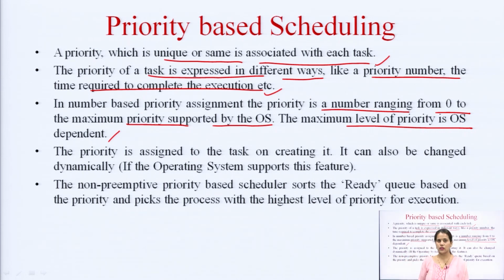So, priority is assigned to the task on creating it, and it can also be changed dynamically if the operating system supports this feature. So, based on the requirement, the priorities of the tasks can be dynamically changed according to the need, and so the different tasks can be executed according to the requirement.